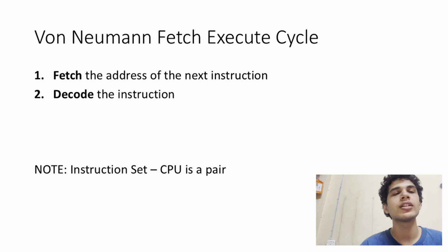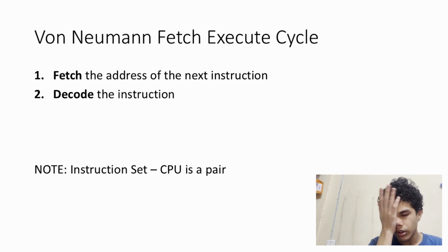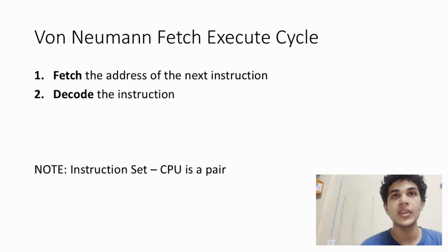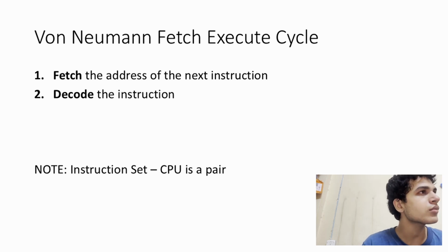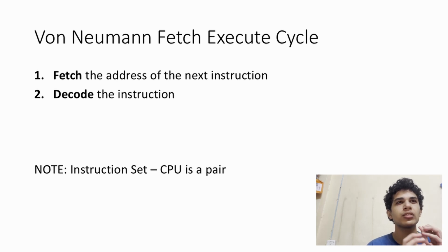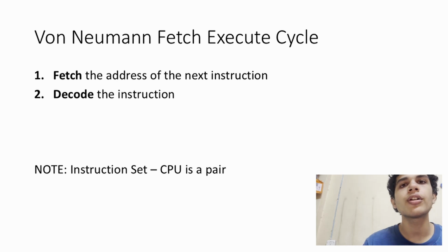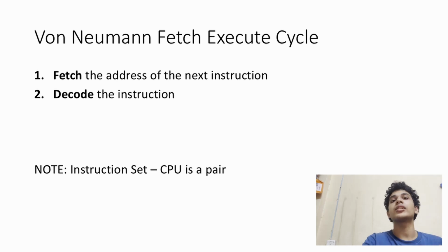And in the case of the CPU used in the 281, they use one-hot encoding, which is basically that based on whichever instruction there is, the decoder gives out a one-hot output of which instruction to carry out. That makes writing the logic for the controller much easier, because then the focus is on sending control signals based on which instruction is there, and not based on how the instruction itself is encoded.